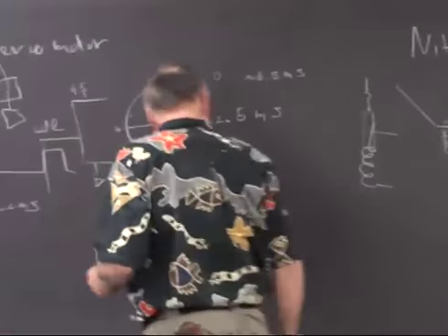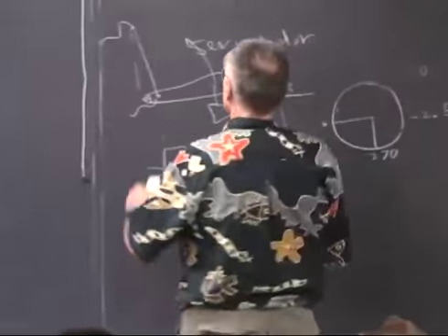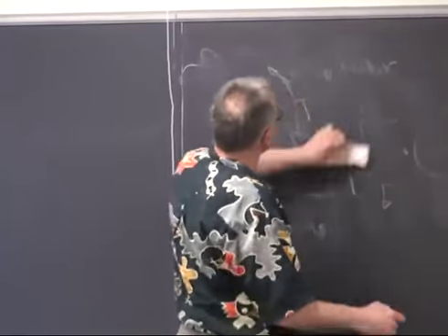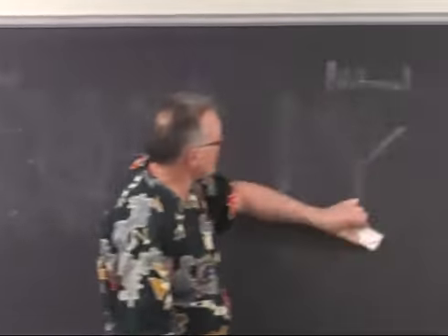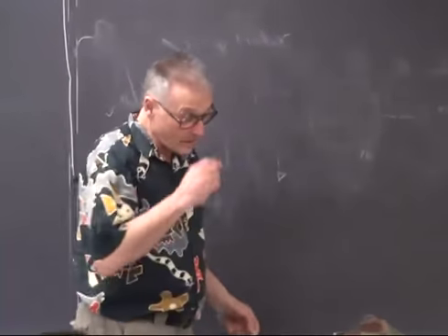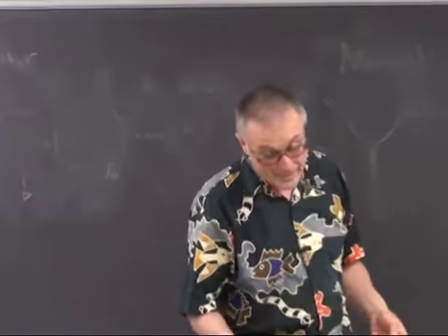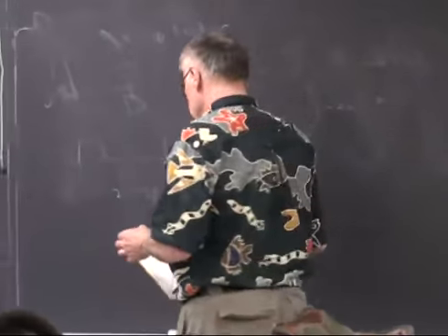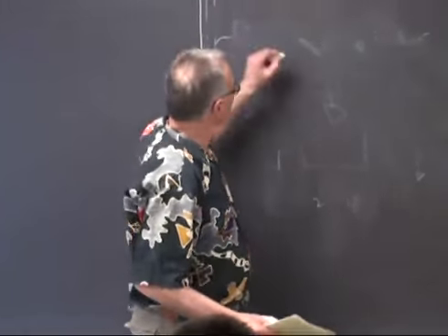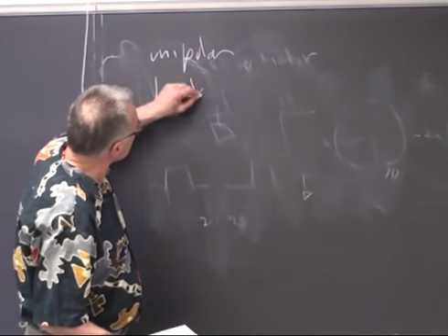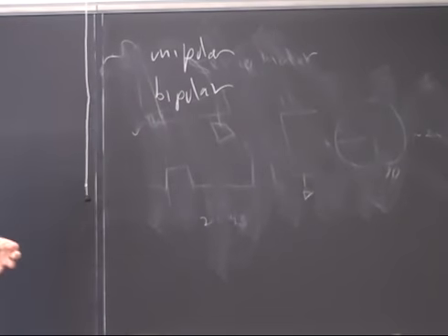So there's lots of ways of doing actuation, and if you've got some weird geometry or something you need to put in a small place or have fast motion, we can talk about it. But what I mostly want to talk about today are stepper motors, partly because a couple of people have already asked me about stepper motors. I'll talk about two kinds, so-called unipolar and bipolar stepper motors, which are different in the way you drive the current through them.